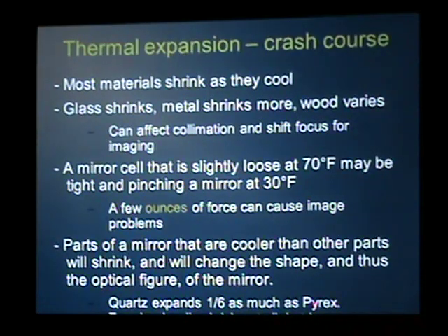Operating on those, we can talk a little bit more about some of the properties of glass and how to debug the system. So mirrors are made of glass. It's a very stable material. Over time, over 100 years, it may not change shape hardly at all, imperceptibly, a tiny fraction of a wavelength. But it will shrink, as almost all materials do, as the temperature drops, by a few parts per million. So your 20-inch mirror, after you drop the temperature, is slightly smaller than 20 inches.